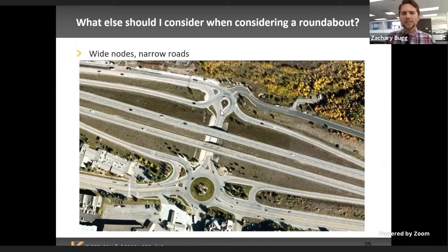This actually has a good example of both a teardrop form and a circular intersection form, whereas at an interchange like this, you don't actually need to allow a U-turn from outside the roundabout to take place. So traffic coming from underneath the bridge doesn't have to yield to any conflicting traffic, and would have the right of way to exit the roundabout. So you're actually able to preserve the width of the undercrossing much better with the roundabout than with a signal.